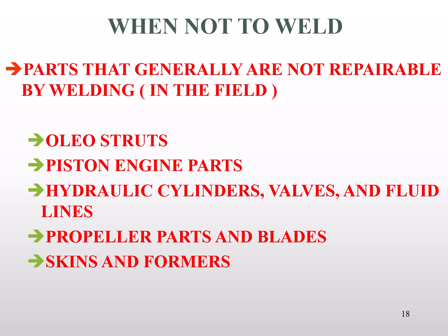Therefore, if we weld, we'll destroy the plating, we'll destroy the strength properties through heat treatment. We never weld any engine part. It is completely forbidden. We would never perform welds on any type of hydraulic cylinder, valves, fluid lines, fittings. If it's hydraulic, most of those parts have gone through a heat treating process. We'll just destroy their properties.